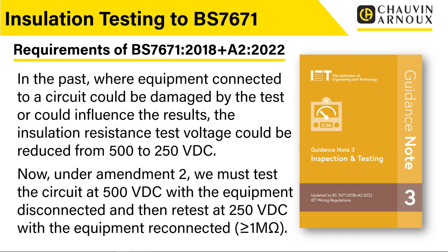But again, there is a change in the regulations, and it has been done for the right reasons, really, to make sure that people are actually testing at the highest voltage they can. I think what was happening was people were just choosing, right, I'm just going to test everything at 250 volts because why wouldn't I? It's easier, I'll just do it at 250 volts and that was it. So I think they're now trying to put the emphasis and say, look, you need to make the effort to test at 500 volts. And the reason we're doing 500 volts is because it is above the supply voltage. We are putting this insulation under some stress.